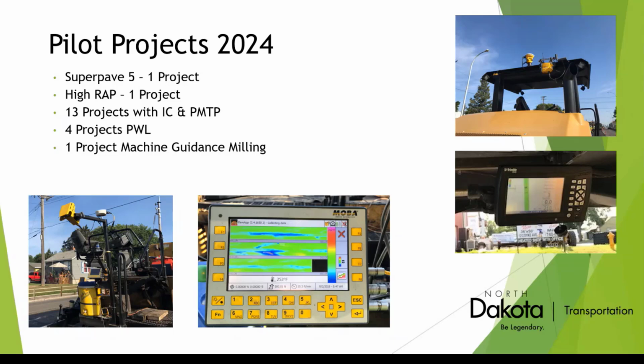It's creating part of your material for your mix, but it's getting the road ready for your paver. And depending on the road and the age and the type of aggregate that's in that pavement, in the South Dakota area, anytime you get into original pavement mixes that had quartzite in them, milling became a slow operation because those diamond bits on that milling head wore out quickly, when they're grinding against a lot of quartzite aggregates. So it was always a fight.